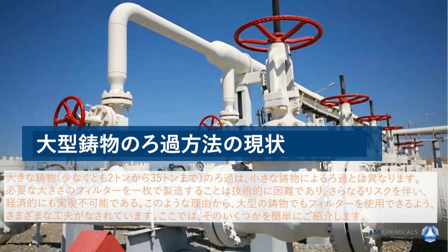Unfortunately, it is usually not possible to reduce the amount of filters to ideally match the number of filters determined by the technicians and optimal for the casting number of ingates. The ideal case would be the placement of one filter, or let me say filtration system, at each ingate, and this should always be positioned as close as possible to the ingate to use the effects of ceramic foam filter